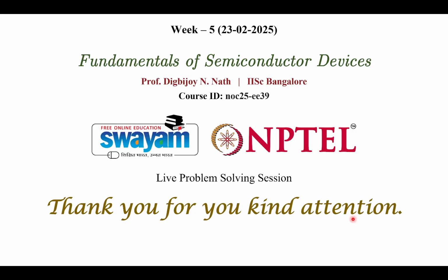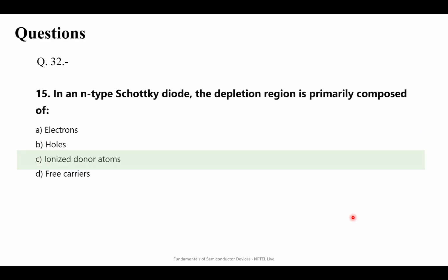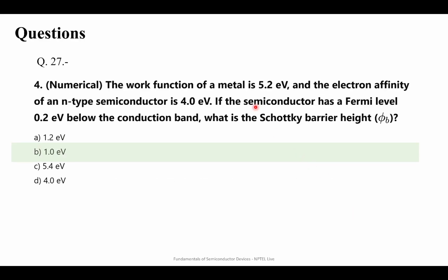So here you have to use the doping density and the Nc value to calculate your Fermi level. So like the question that I had shared here, I had shared that the electron affinity I have given you is 4 electron volts. In your question also the electron affinity is 4 electron volts, and the work function you are given 5 electron volts. For me work function is 5.2, so you just have to use 5 electron volts as work function.